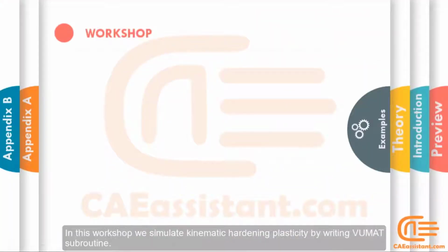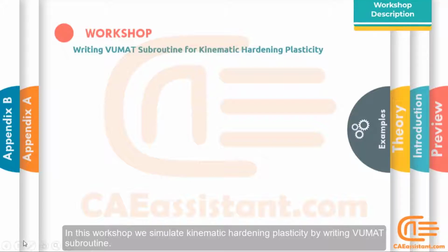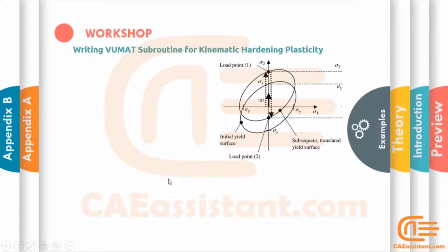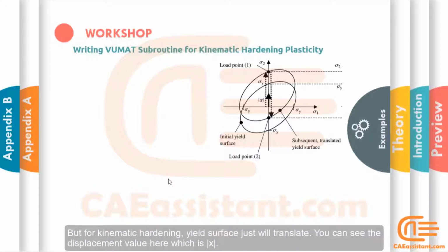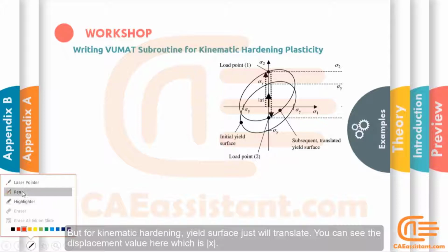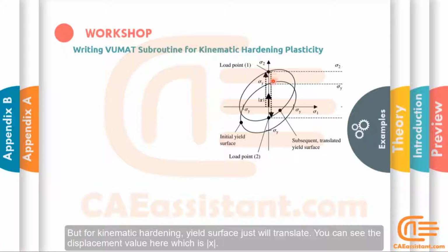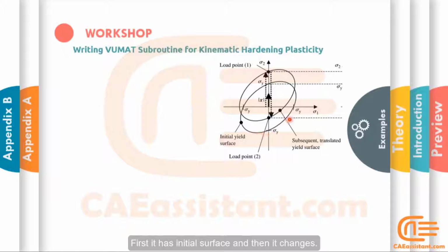Hello guys! In this workshop we simulate kinematic hardening plasticity by writing the UMAT subroutine. Pay attention, in kinematic hardening behavior, the yield surface will shift. In isotropic hardening, the yield surface will be larger. But for kinematic hardening, the yield surface will just translate. You can see the displacement value here, which is x. First, it has an initial surface and then it changes.